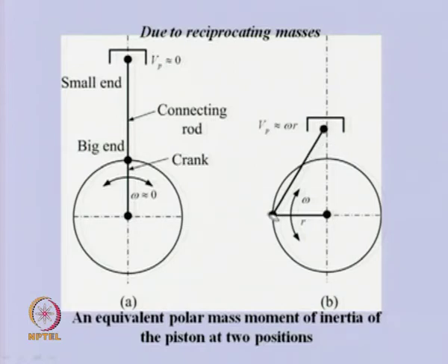So, that much inertia it will impart. You can see that the first case imparts 0 inertia, and in the second case it is exactly the same as the reciprocating part. So, to approximate, we can take the average of these two as the rotary inertia of the piston.